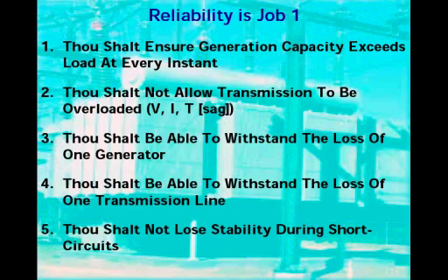They're responsible for making sure that load is always met, or that the supply of electricity meets the demand of the consumer. First of all, they have to make sure they have enough generation capacity at the ready. Furthermore, that power will not help all the people if it can't get to them. So they have to make sure none of the lines are overloaded. That is, when the current gets too big, you have too much resistive loss and heat that will cause the lines to sag. We don't let that happen.